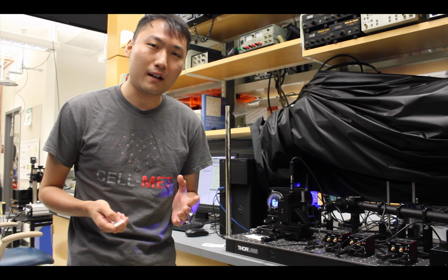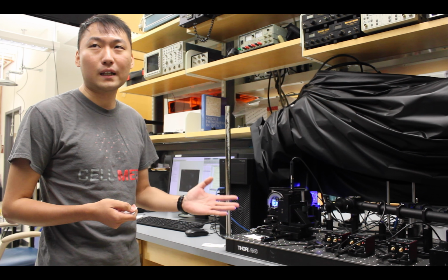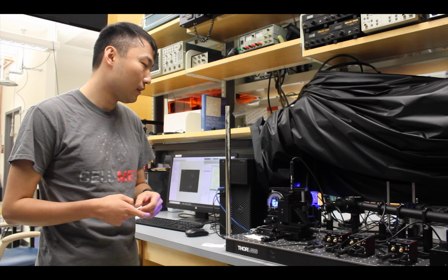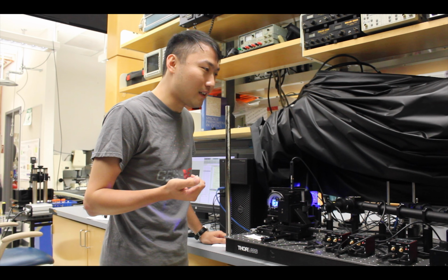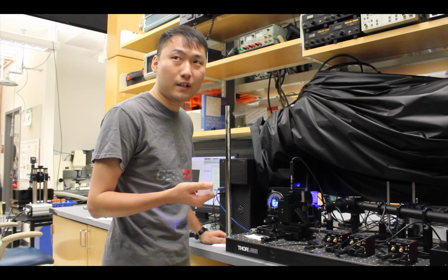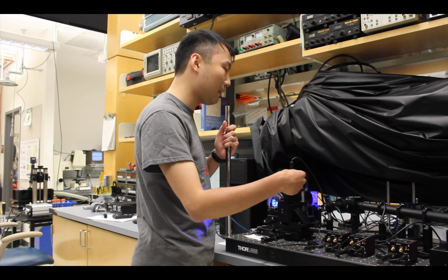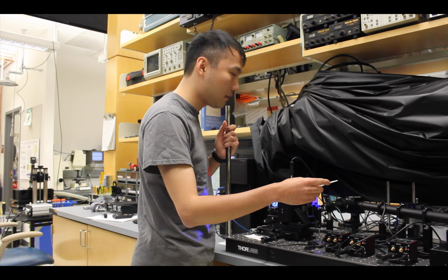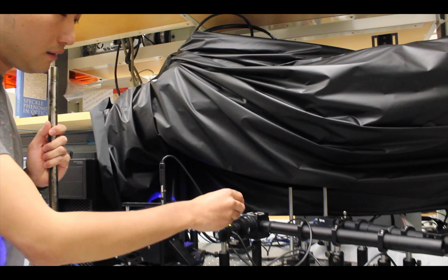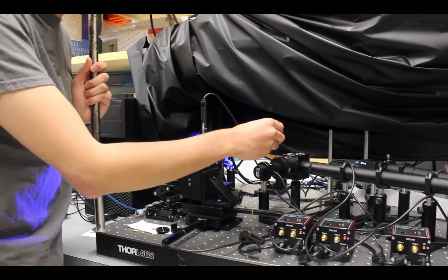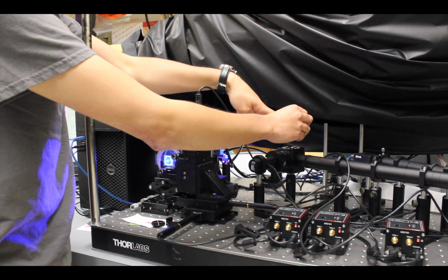The setup, or the device, I'm going to show you today is this microscope called ASOM, the Adaptive Scanning Optical Microscope. This microscope is quite an elegantly designed device for optical imaging, in that it has many optical components and a complicated light path. Basically how it works is that you have a light source here, which is a blue LED, and there's a beam splitter here. The light will bounce onto the beam splitter